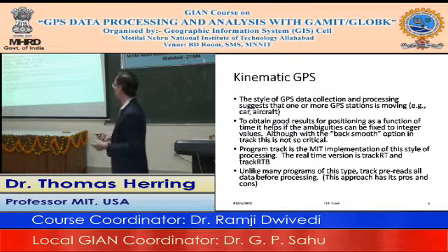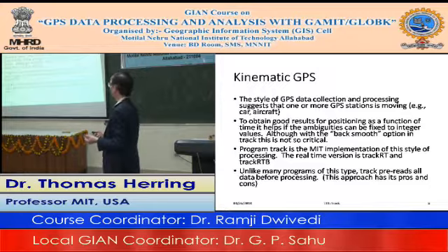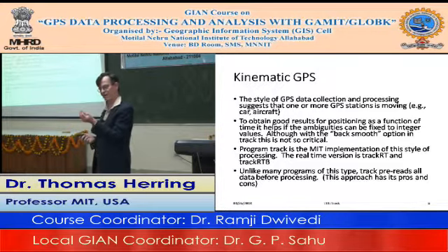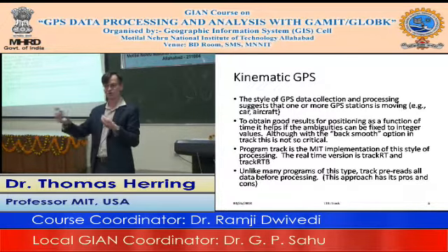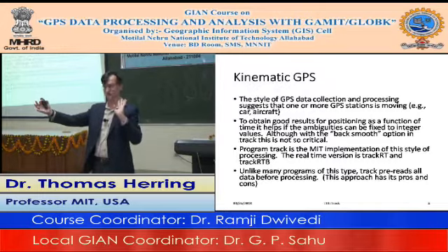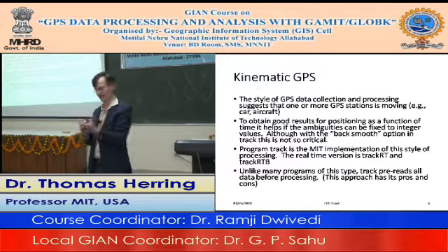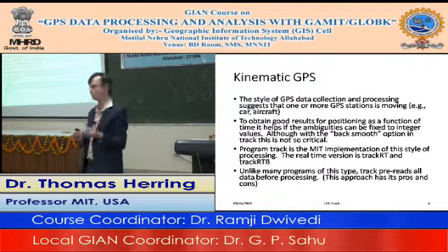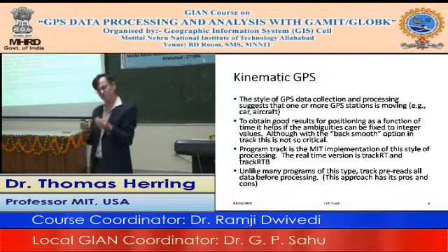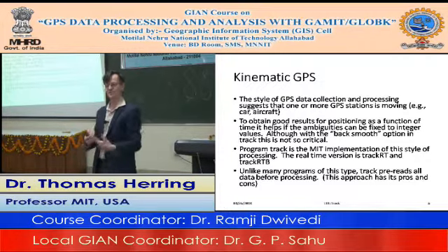Kinematic data in general is more complicated than the standard static positioning. And that's primarily because in kinematic movement, you are moving the receiver, or the antenna, as you move it around, it's going into environments where there could be sky blockage at various points. There is actually the whole kinematic motion of the antenna and the tracking loops in the receivers that sometimes don't behave well. So in general, this is not quite as turnkey as the GAMIT processing is.